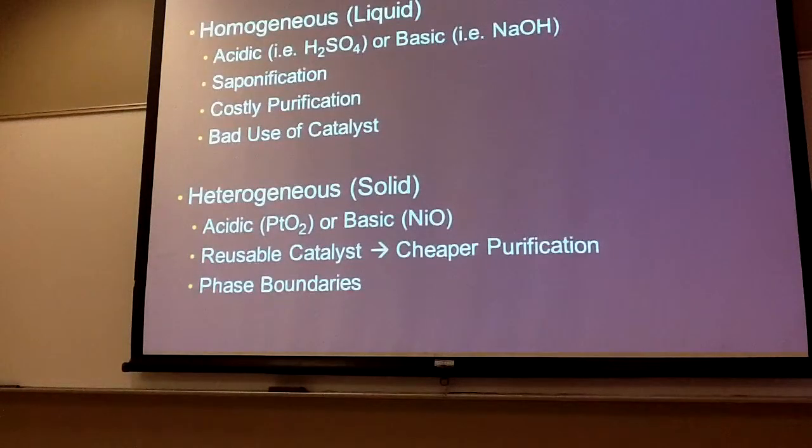a big plus. However, if there's any free fatty acids at all, the sodium hydroxide reacts directly with the free fatty acids through a saponification reaction to produce soap rather than biodiesel, which as a result leads to really expensive purification costs, and your catalyst cannot be reused because it's being reacted.